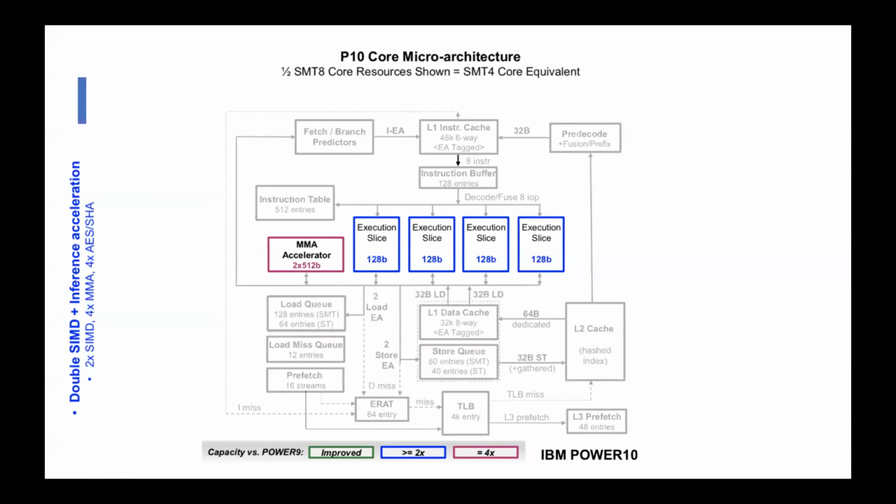And remember, this MMA accelerator is not just for lower precision, it supports double precision and single precision, right? That way all the HPC needs will also get fulfilled. In terms of the benchmarks that the Professor showed in the previous slide, a lot of those benchmarks, including LinPack, including DGEMM and all that stuff, can run at a much faster rate in the P10.